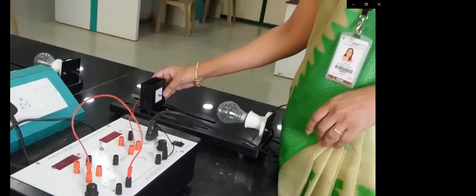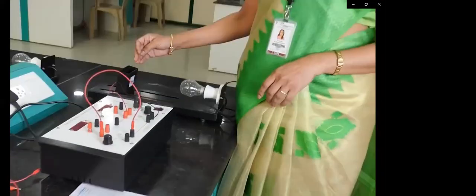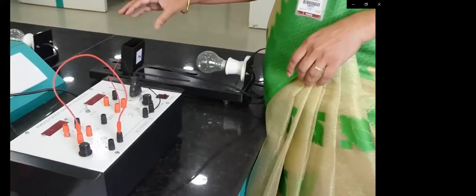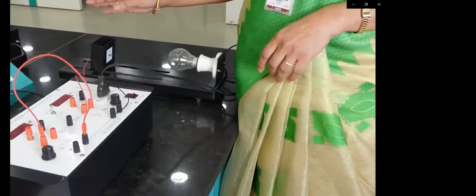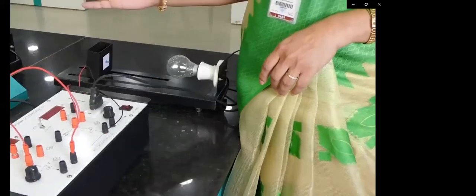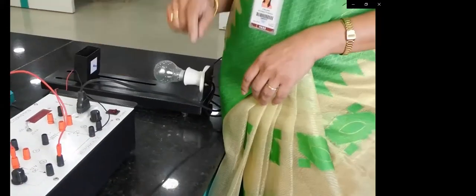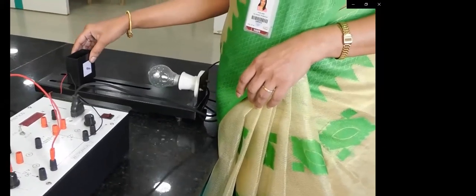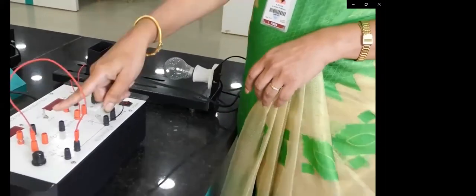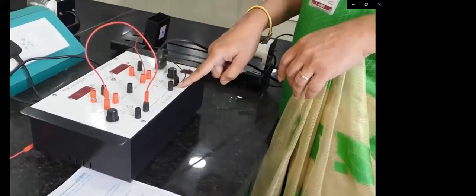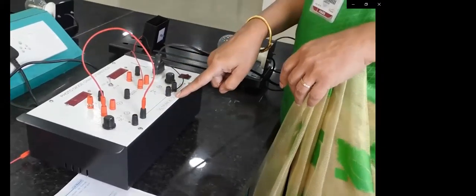Let me tell you about the photodiode. A photodiode is a two-terminal PN junction device which operates in the reverse mode. When light from the external source falls onto the photodiode, the thermally generated electron hole pairs will be swept across the junction because of the reverse voltage we are applying. So we always connect or use it in the reverse bias mode. In reverse bias, we connect the positive of the power supply to the negative of the photodiode.